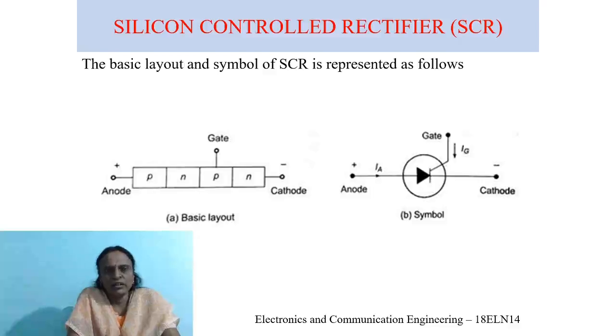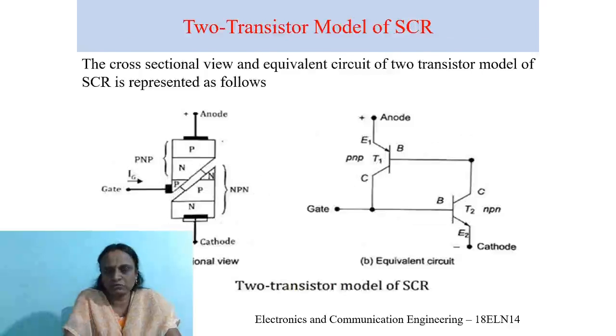However, because of regenerative action, removing the gate current does not cause the device to turn off. Still, the SCR will be in on mode. Okay. So this is the two transistor model of an SCR, and the cross-sectional view and equivalent view of the